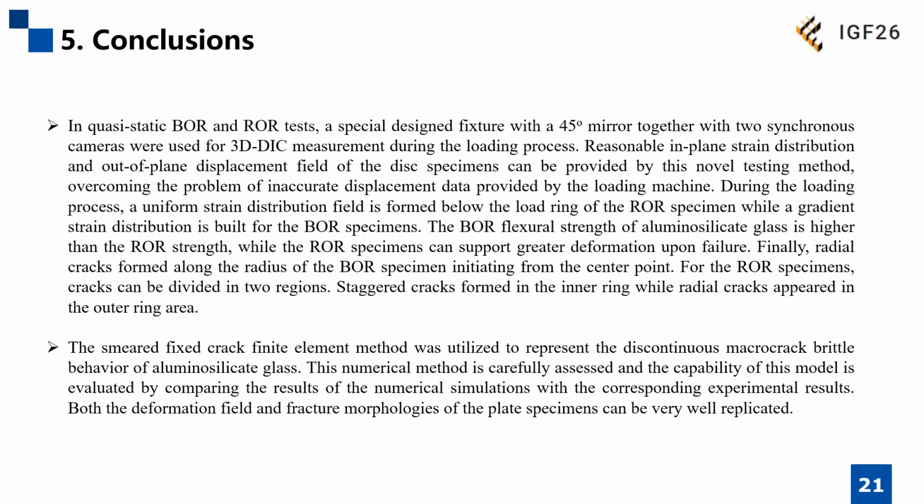Finally, there are some conclusions for this study. In quasi-static ball-on-ring and ring-on-ring tests, a specially designed fixture with a 45 degree mirror together with 2 cameras was used for 3D DIC measurement during the loading process. Reasonable in-plane strain distribution and out-of-plane displacement field of the disc specimens can be provided by this novel testing method, overcoming the problem of inaccurate displacement data provided by the loading machine.